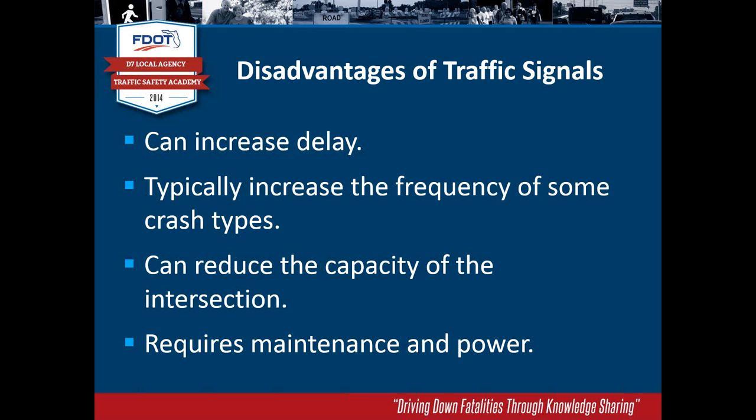Let's say you had 10 traffic signal heads that were burning. Each bulb was a 135 watt bulb, and so if you've got 10 signals burning, you're consuming 1,350 watts of power every single hour of the day.